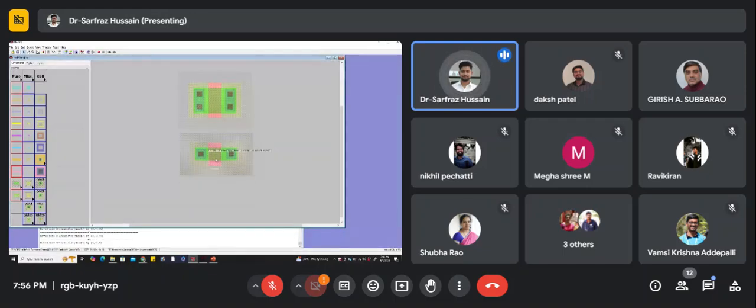So like this, you can bring this one down so that both the polysilicons are properly connected. Okay. So now we can actually connect these 2 layers. Once you connect these 2, again save it and check the DRC for errors.